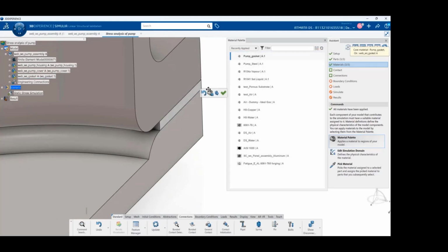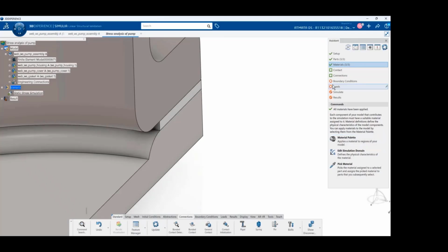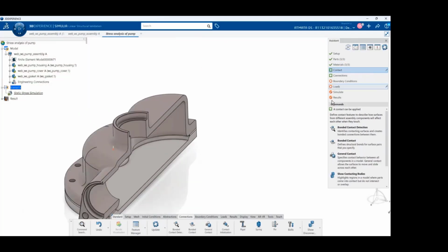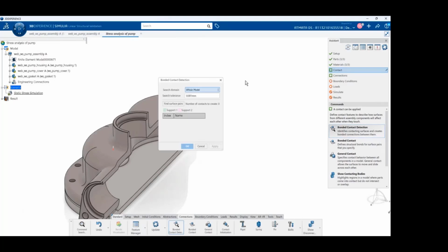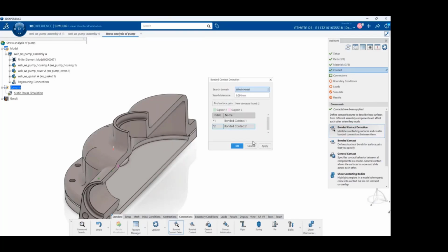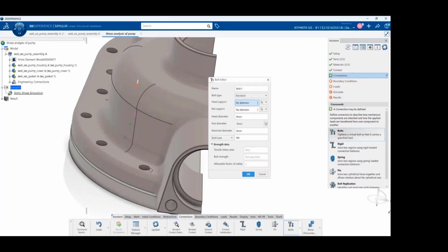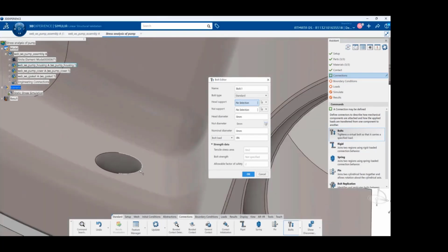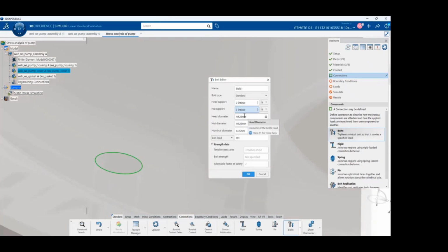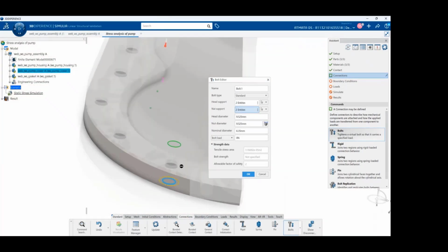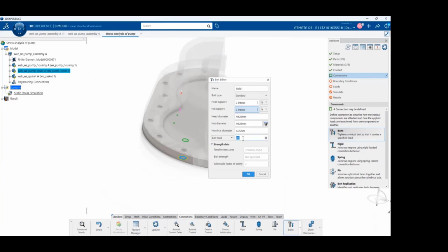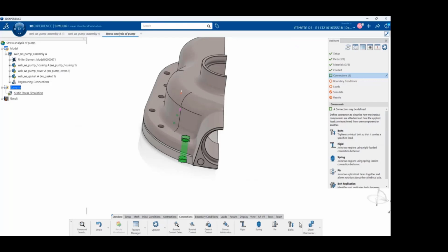Even though, see, the fundamentals remain the same, only the tool usage is where it differs. Whatever fundamentals or approach you use for solving a linear static analysis is much the same for both. So to create a virtual bolt, I will just select this edge. Yes, so automatically the other edge will be selected, and the bolt load, whatever it is defined, 500 Newton, I can straight away define it.